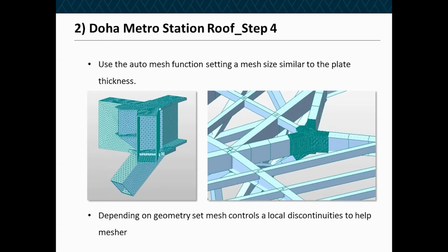And all of this can be done provided you stay in the same geospatial coordinates. So you export from MIDAS Civil into AutoCAD in the same coordinates, into FEA in the same coordinates, and then back from FEA into Civil in the same coordinates. And all you have to do then is use the rigid link command to connect your connection into your frame model center lines. Simple, yeah? Dead easy.